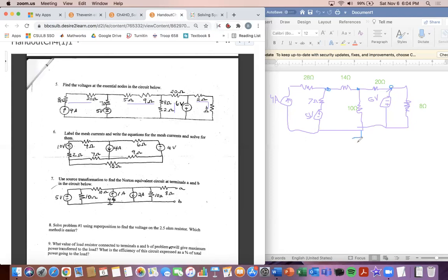And this is connected to the most elements. So that's why I created ground. So this would be V1 here. This would be V2, V3. And if it was connected between the 2, it would actually be like here, the voltage source, but it's not. So it's not connected. But so we don't need to form any super nodes. However, we're going to have to solve this using the node voltage method. So we're going to have to create some of our equations.